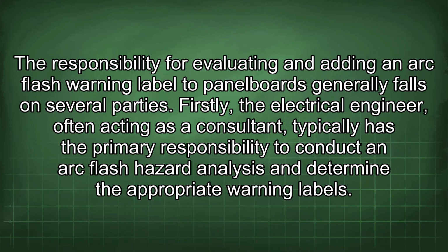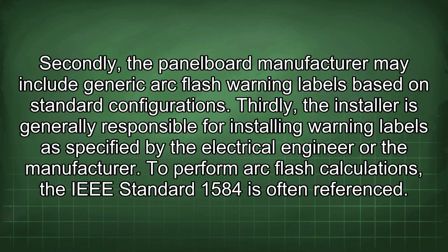The responsibility for evaluating and adding an arc flash warning label to panel boards generally falls on several parties. Firstly, the electrical engineer, often acting as a consultant, typically has the primary responsibility to conduct an arc flash hazard analysis and determine the appropriate warning labels. Secondly, the panel board manufacturer may include generic arc flash warning labels based on standard configurations. Thirdly, the installer is generally responsible for installing warning labels as specified by the electrical engineer or the manufacturer.